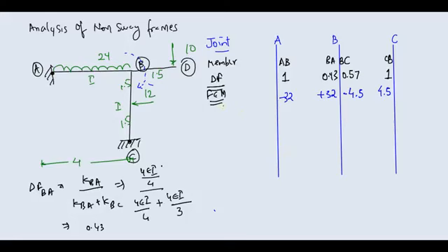Once you have your FEM, the next step is to look if you have an overhang or a hinge, or an end joint. In this particular case you are having an overhang. So you have to balance this joint B, because joint B will be having a net moment of 10 into 1.5 because of this overhang. So I think you will have a net moment of 15. So at this joint here, I am doing it with red, I want this moment to be equal to plus 15.